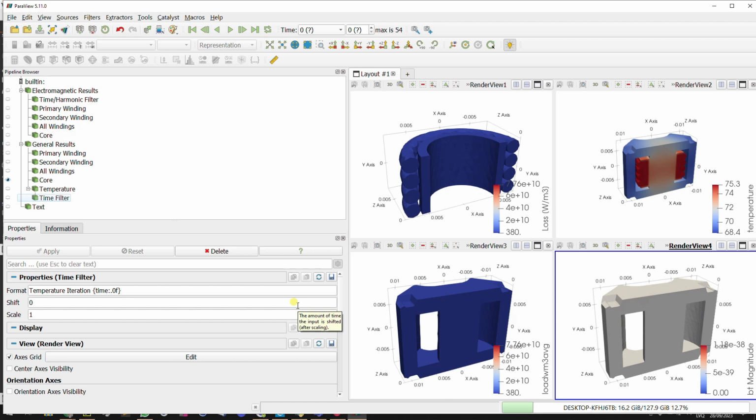And how about treating AC and DC? Yes, easily. With the transient solver, as I showed you here, you can treat any waveform. I consider DC to be basically identical to AC, but with zero frequency. So this is how we often treat DC biased simulations.